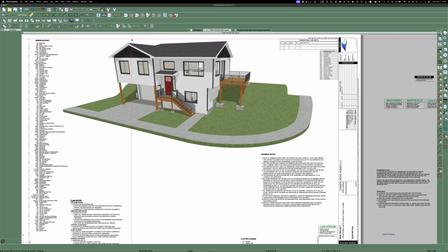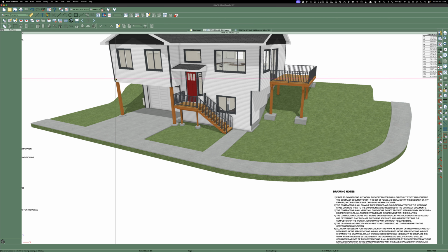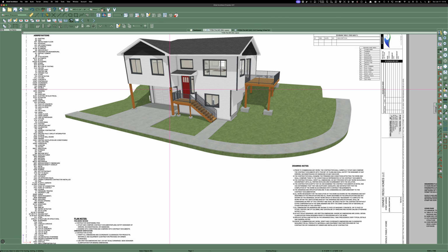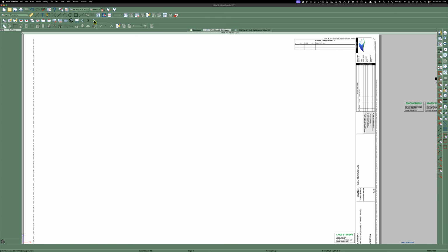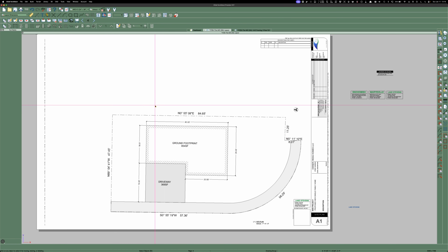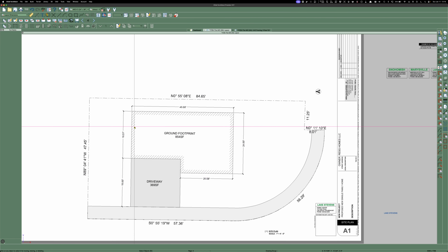And the only way to fit the plan that the builder had was to stick this out 9'7" onto some beams. What I've done is I put the beam up inside the wall framing because I want to keep it out of the weather. Some people like to see the beam. I'm more inclined to never let the beam ever get wet, or the top of the posts. So if the city of Lake Stevens will let that go, then we will have it. Here's the ground footprint. So we'll see.